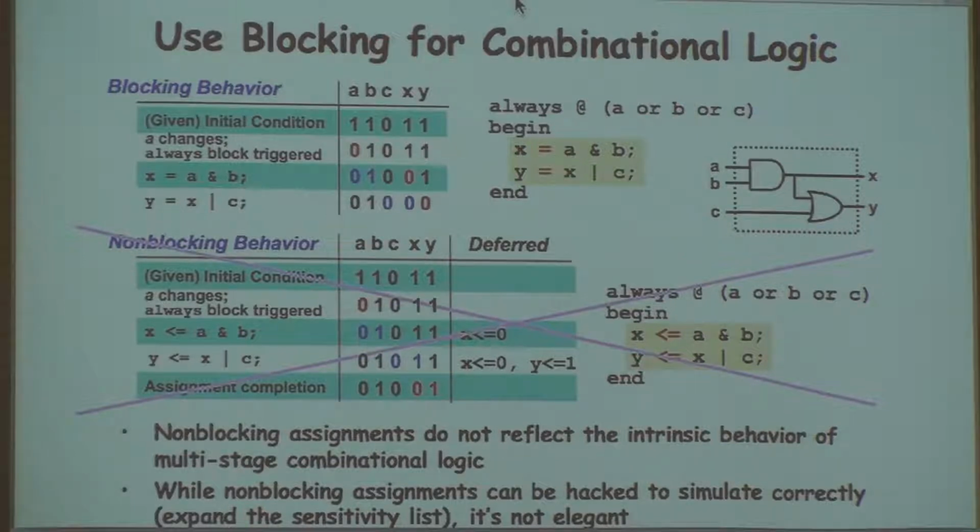So, can you all write a multiplexer 3 different ways in Verilog? You could use an if statement, which would instantiate a multiplexer in an always block. You could use a case statement in an always block, which would instantiate a multiplexer. Or you could use a conditional assign, which is combinatorial. All of these are combinatorial. Is this familiar to you? Are you all okay?